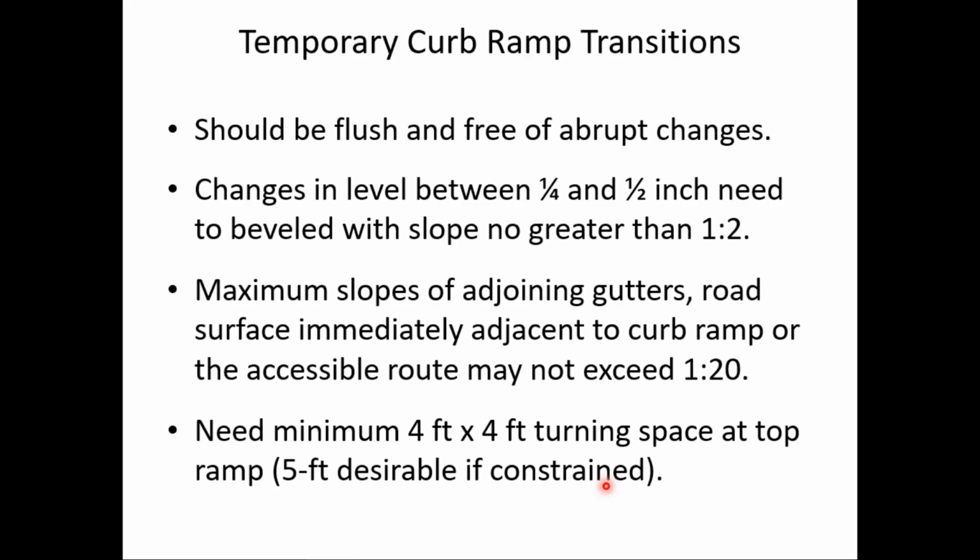And don't forget there should be a minimum 4 foot by 4 foot turning space at the top of the ramp. Desirably 5 feet if it's constrained. If there's a guard or a rail or something, then desirably that turning space should be 5 feet in the direction of travel.